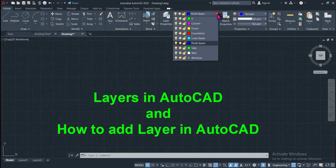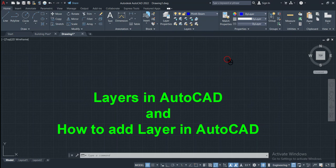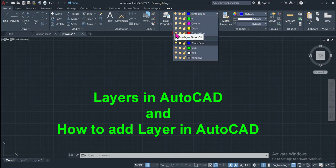So now this is a beam, the plane beam layer is active, and these are the different tools that are associated with the layers. Here the first one is this, in a bulb form. From here you can turn a layer on or off. You will learn this tool with the help of an example.